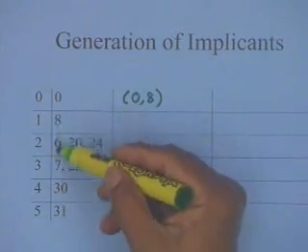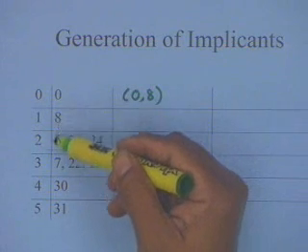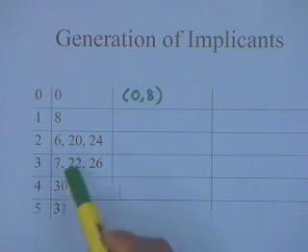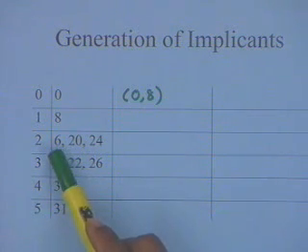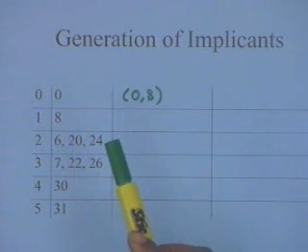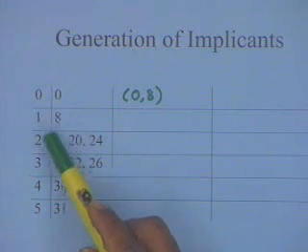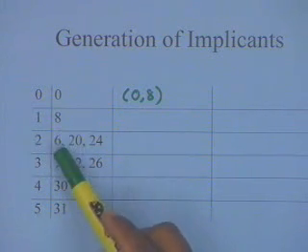Now I consider the minterm here with the minterms in this group. If you consider the combination of 8 and 6, it satisfies only the first condition, that the difference is 2, which is 2 raised to the power 1. But it does not satisfy the second condition, because the minterm with the larger value should have more ones. Here the minterm with the larger value is 8, and it has one less 1 than 6.